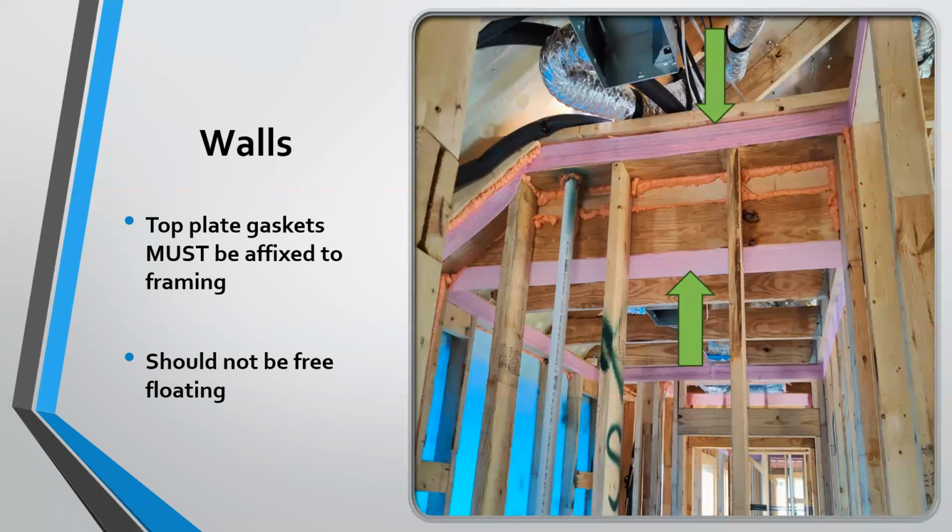Walls, and when it says in code, it says exterior walls. In our world for energy, that includes, and I know it's kind of a tough term to try to say, interior walls as exterior walls, which is not true, but the top of interior walls intersect the attic, which is unconditioned space. An exterior wall actually separates the outside unconditioned space from the inside conditioned space. The top of those walls and knee walls do the same thing.